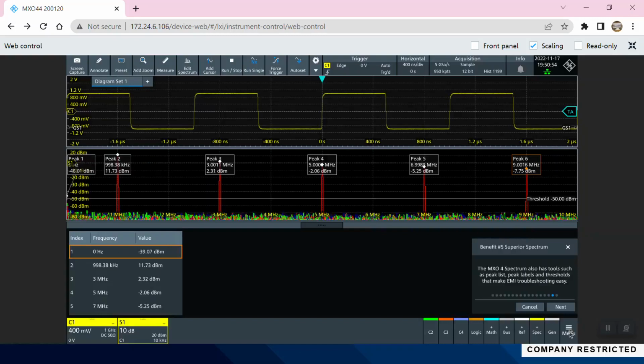And imagine having the ability to have the FFT update 45,000 times per second. You're going to be able to move the near-field probe around rapidly and still capture events as you move around. It's going to be able to keep pace with your movements. You're going to be able to capture spurious events, etc. So really powerful for lively, and dynamic spectrum analysis use cases.